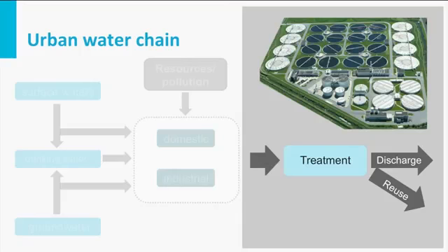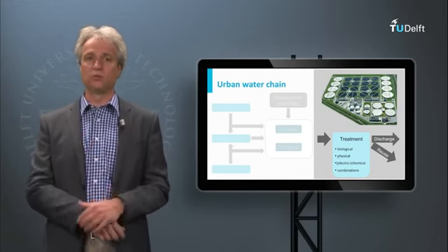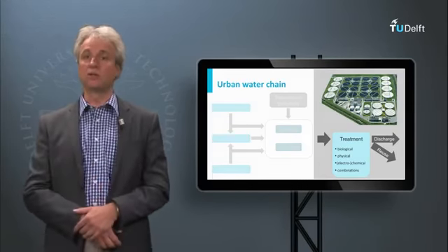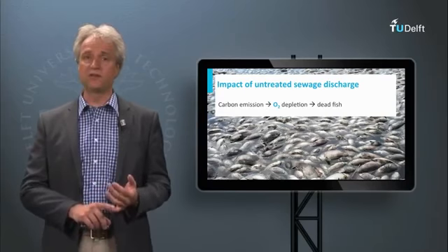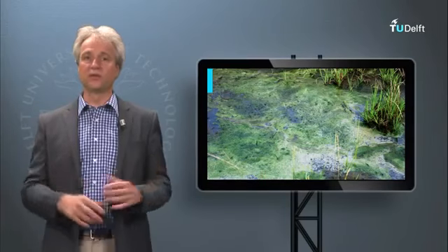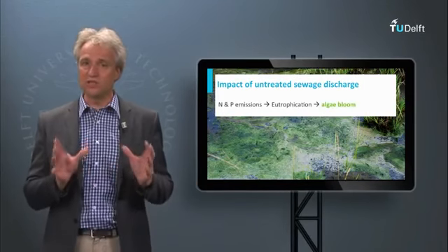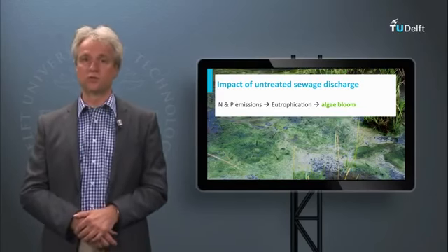The sewage treatment plant consists of several functional units, each targeting a specific group of pollutants. Such a unit may consist of physical treatment, chemical treatment, biological treatment, electrochemical treatment, or combinations of these types of treatment. We have to realize that every single cubic meter of drinking water will ultimately become 1 cubic meter of wastewater, and that may impact many cubic meters of surface water, or even groundwater, when it is discharged without treatment. Since the self-attenuation of these waters is very limited, such discharge will lead to severe environmental impacts. In order to protect the environment, financial investments have to be made to establish treatment technologies. And particularly in congested areas or urban settlements, uncontrolled discharge of large sewage flows is considered problematic.